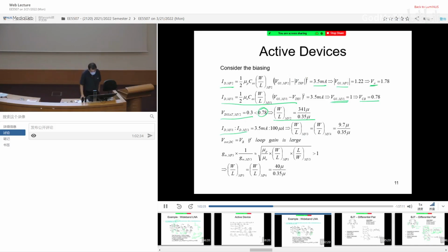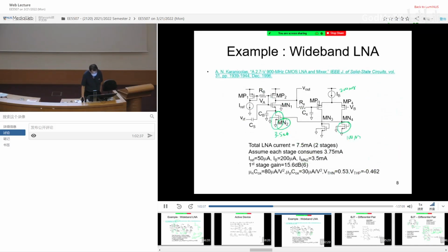Now, this doesn't tell all the story. It still didn't give you an idea how to design this op-amp over here. Now remember, do you know why for an op-amp, due to the feedback, V plus is approximately equal to V negative? Do you know why? Because of the virtual short, mainly because the loop gain is big. Because the loop gain is big, it forces the difference to be very, very small. So the key is actually the loop gain. It needs to be much bigger than 1.